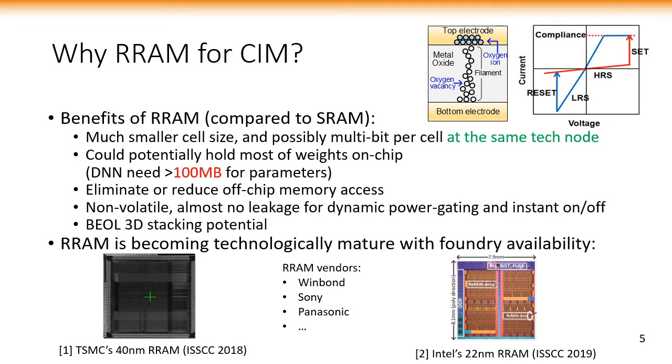Why RRAM for computing memory? First of all, RRAM is a two-terminal emerging non-volatile memory. It consists of a three-layer stack: the top electrode, metal oxide, and bottom electrode. The resistance of this device can be changed depending on the voltage input.